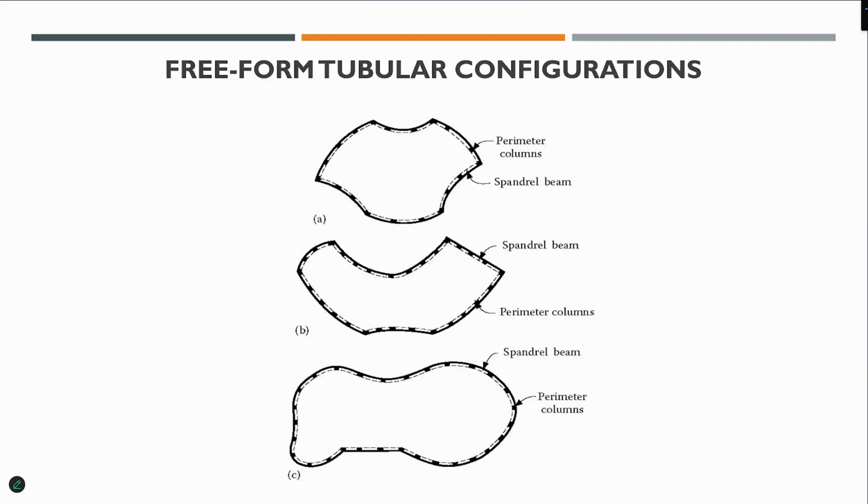Then architects got more adventurous when they saw this thing. Oh my God, this is great. Then they start to draw all these funny shapes. And then engineers try to fit the tube around those because the tubular system seems to work on irregular buildings also, right? Because now there's no problem of the core trying to connect to that. You can just have any shape. So these are the buildings coming up, and then these are the tubes around those. You can see the columns closely spaced. So engineers try to then follow the architects on irregular plans using these irregular tubes.